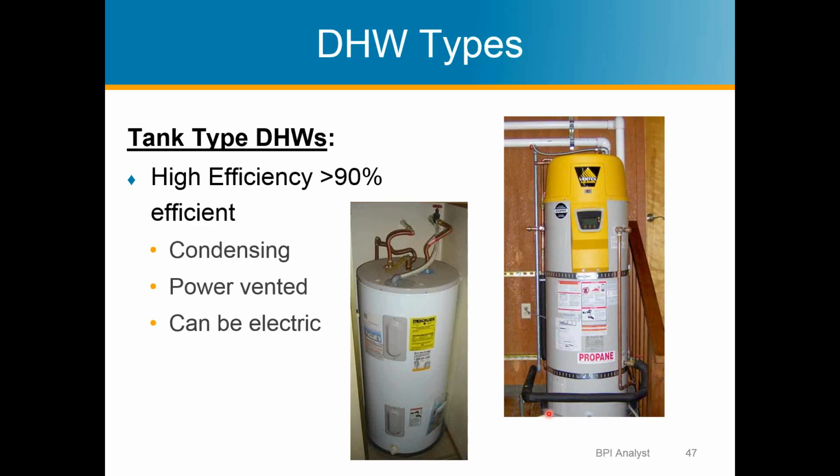So we'll start on water heaters. We'll start with the highly efficient, the greater than 90% efficient. You've got condensing, this is a condensing propane water heater. The A.O. Smith brand makes several good condensing ones that I've installed a lot of. These can also go up to 100,000 BTUs, which is probably a small one. They're condensing, but they're also modulating, so they would have maybe a minimum input of 20,000 BTUs per hour and a maximum of 100,000 or 200,000 BTUs, depending on demand from the water system.